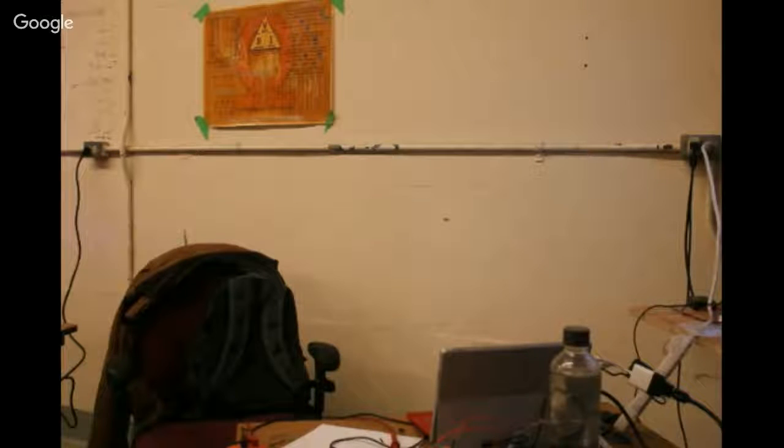No, that looks great. The only one, so I'm probably not doing anything about this now, but as you get more soldering done, the color of that one, you can see that dull color. That means that you were a little bit quick on pulling the iron off, and the solder wasn't quite as firm. On these ones it's just fine, but when you're looking for a more permanent circuit, you need to watch that.